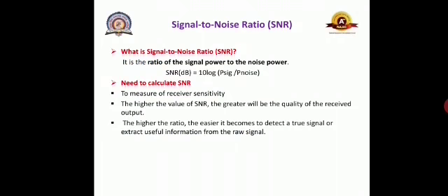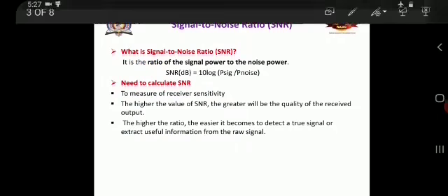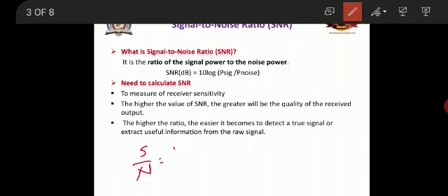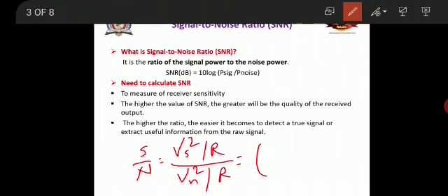This can also be calculated in the form of the signal voltage and noise voltage. So it is like this. If you take the S by N ratio equal to the electrical power, signal power can be written as the signal voltage squared divided by the resistance R, and the noise voltage squared divided by the resistance R. So it becomes Vs by Vn squared.